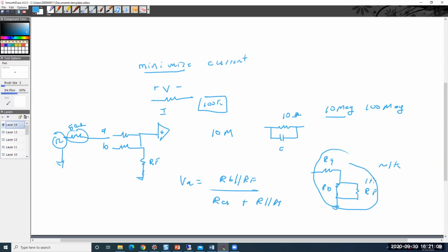And so if I started here at 1K and I wanted gains, RB would be less than that. And so I could end up with an equivalent resistance of like 50 or 100. So by starting at 100 kilo ohms, it makes sure that when I'm done scaling everything and things are in parallel and series, I'm not getting this.